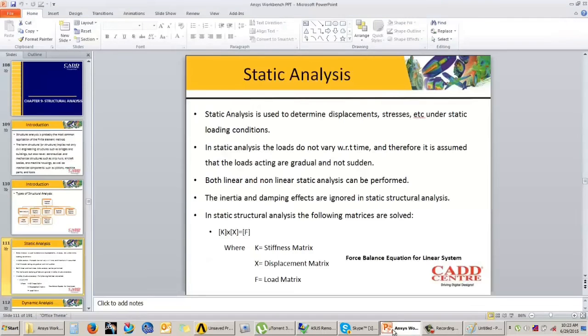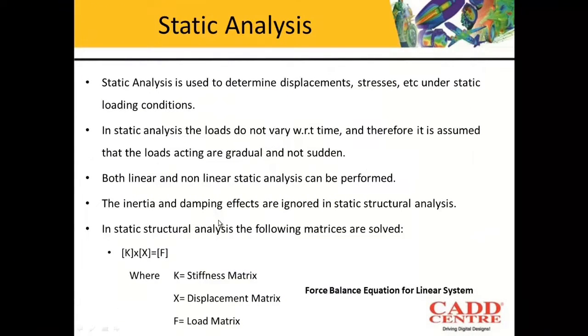Another point that you should know about static analysis is that the inertia and the damping effects are ignored. We do not consider the inertia and damping effects when we are solving the static structural analysis. And if you want to understand the matrices that are solved in the software, it is K into X is equal to F. K is the stiffness matrix, X is the displacement matrix, and F is the load matrix.